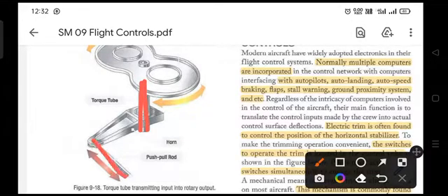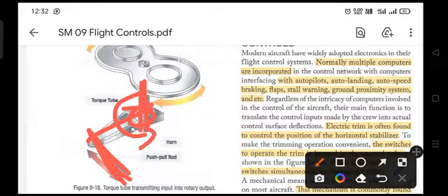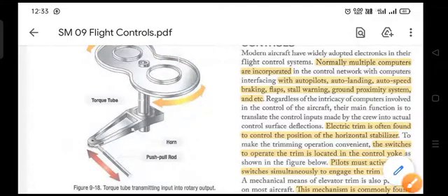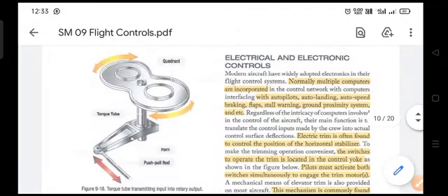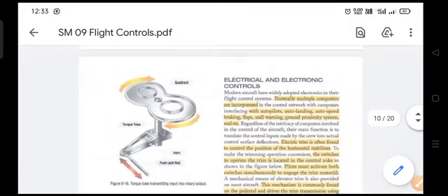Okay, like you have a control linkage mounted like this, which is hinged over here. Now when you push or pull this rod, this torque tube will also rotate accordingly, either in a clockwise or anti-clockwise direction, and that will further rotate this particular bell crank, or rather what you should call a quadrant. There may be something else as well. So the torque tube is basically used to transfer the motion. It is transferring the motion with the help of some torque that is applied on it.